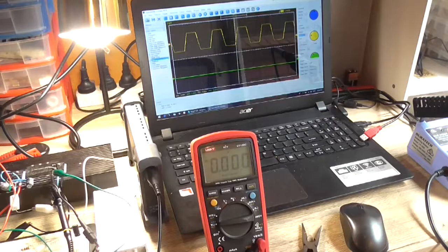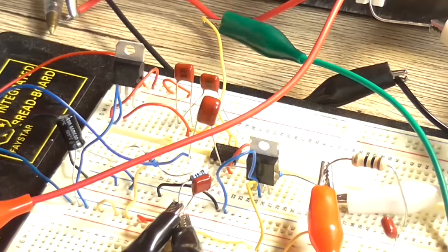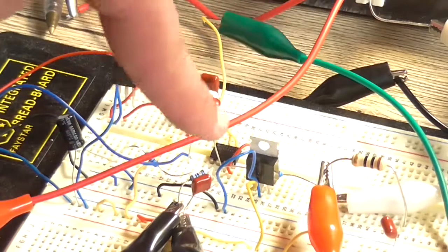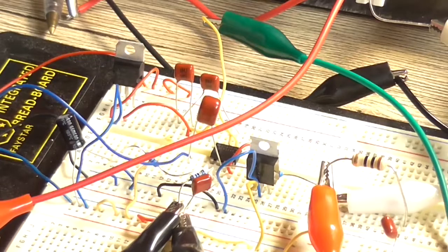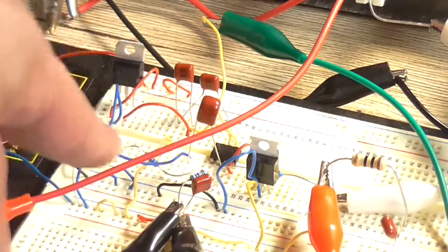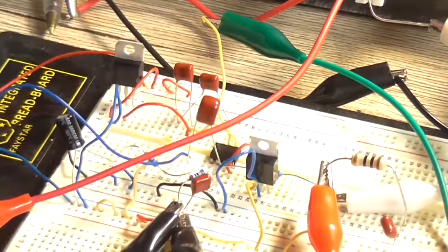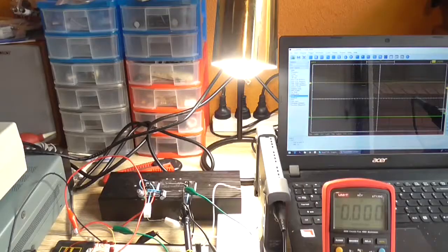So what do we do about that? Well, why don't we actually just try plus minus 15 volt regulators? Okay, so I've got a 7815 and a 7915 voltage regulator on the positive and negative rails respectively now, so we should be getting a good plus minus 15 volt to the OpAmp. I'm at 1 volt 1 kilohertz on the DDS, so I'll turn on the load now. It's still clipping badly.